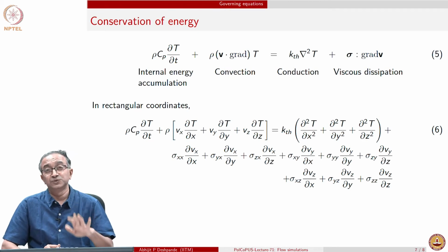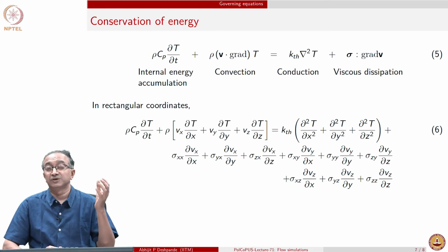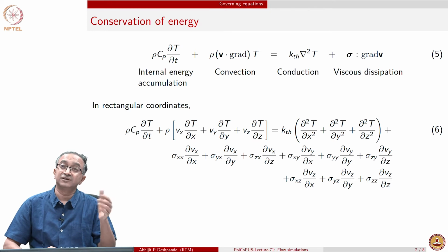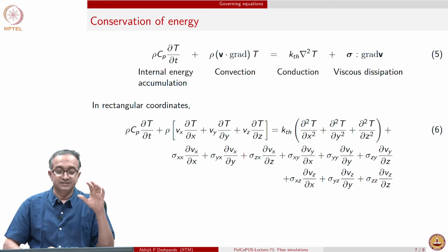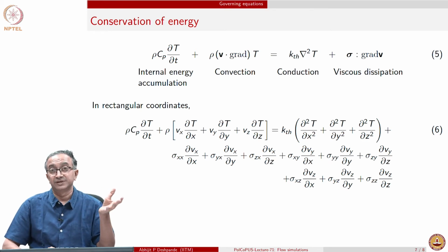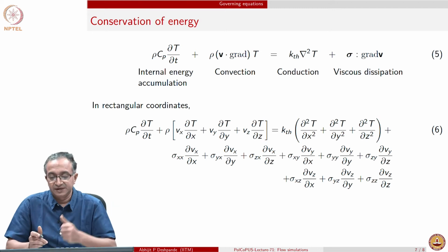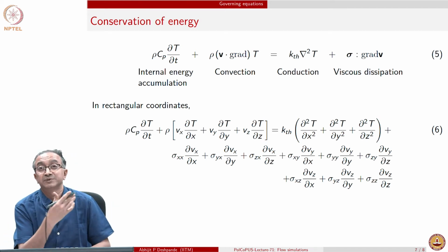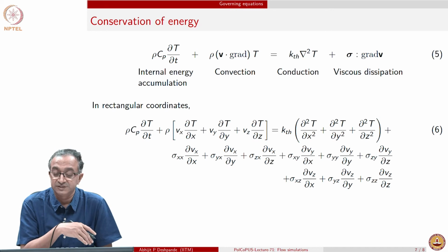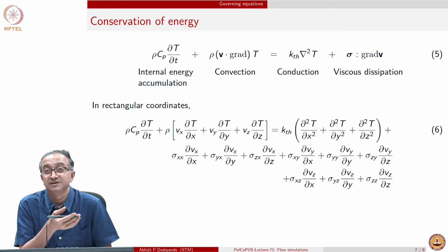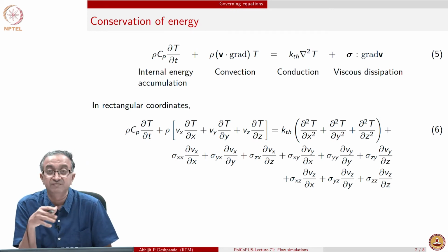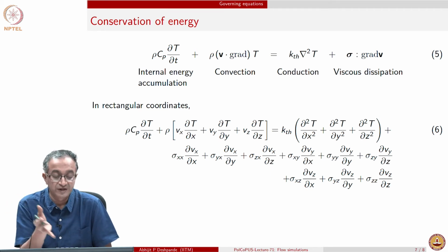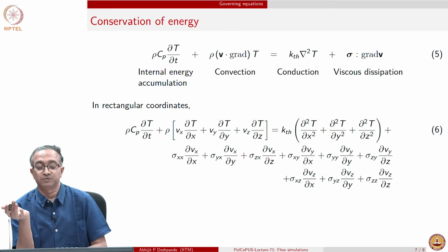We have also to do the energy balance because of the associated heating and cooling that goes on in a polymer processing operation, as well as changes in polymer that may take place due to the temperature change. For example, the conductivity of the polymer itself, its specific heat may change, its viscosity may change as a function of temperature. And so, we need to know the overall behavior of the polymeric system under non-isothermal conditions when we have the energy balance as the key requirement.